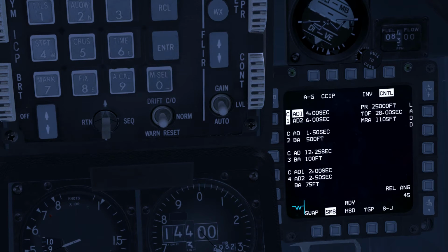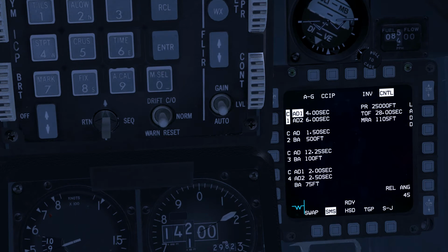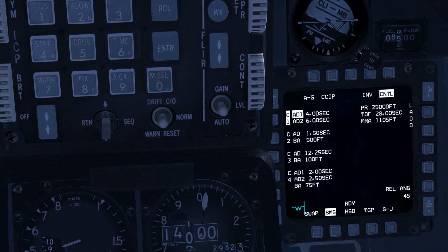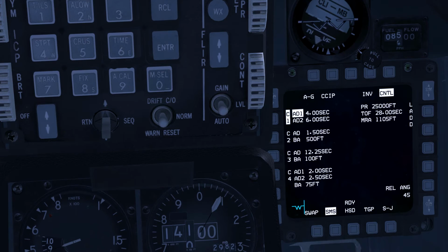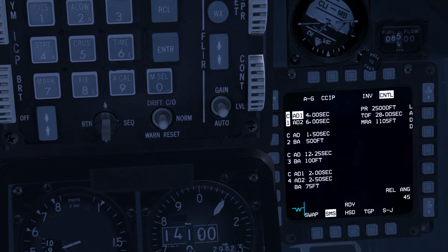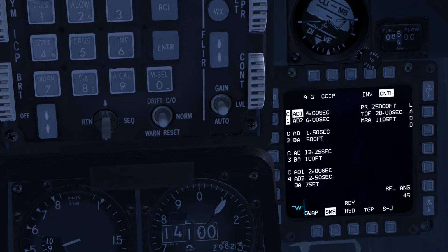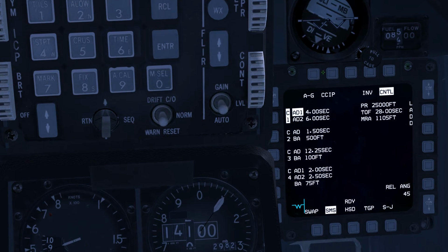The type of fusing for a Mark 80 series of bombs, which the BDU-33 practice bombs are simulating, would depend on the era and theatre simulated. But we're going to make the safe assumption that we're using an FMU-139 nose fuse. The FMU-139 has arming delays of 4, 6, 7, 10, 14 and 20 seconds on the faceplate for low drag bombs. We're going to select the 4-second option, adding a 15% tolerance.